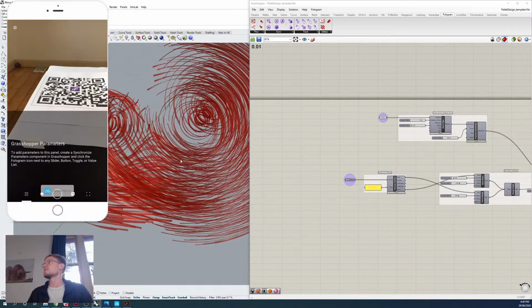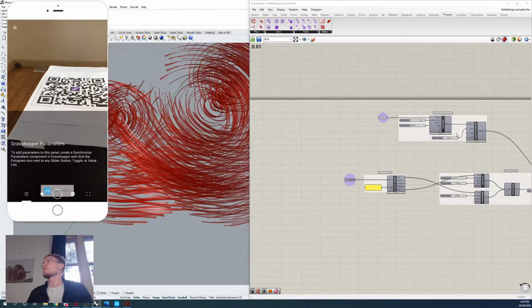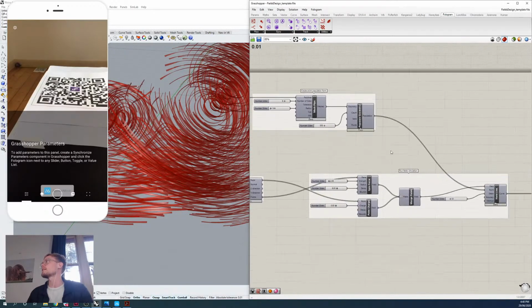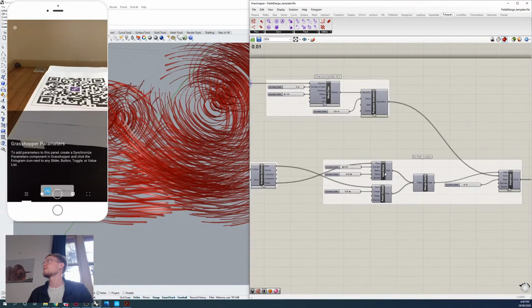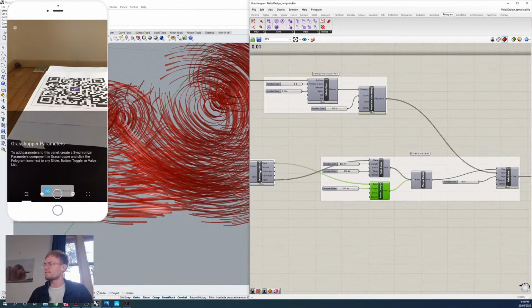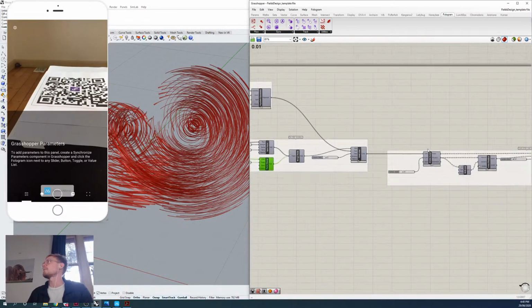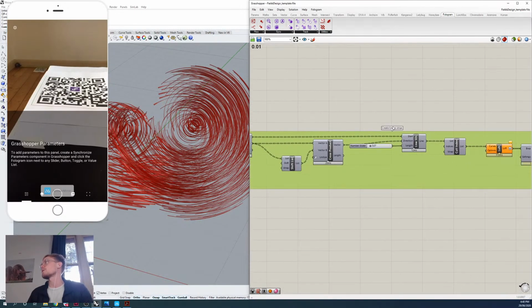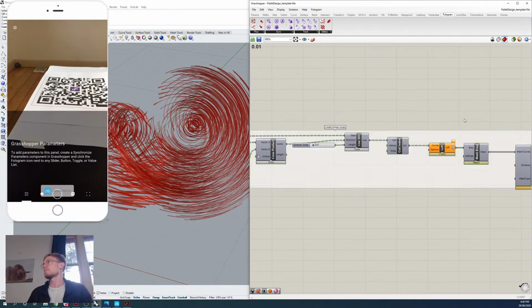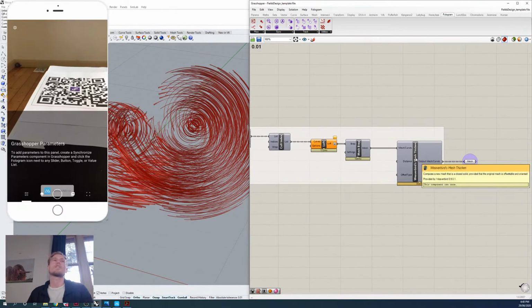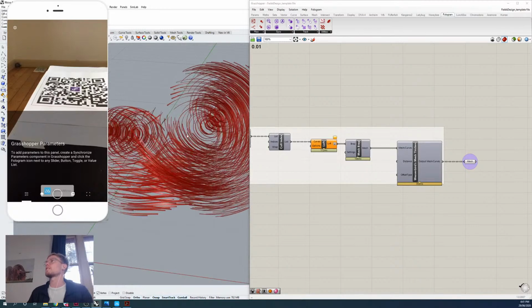Basically, if you've used the fields components in Grasshopper before, you'd be a little bit familiar with them. We're running a very simple field simulation with some spin forces and some point charges. That creates a field of vectors where we specify some starting points, and each of those starting points step through those vectors and create these long curves. Then over here in the definition, I'm writing a very simple timber strip behavioral algorithm, not totally optimized for fabrication, but it gives you an idea of what your timber strips might look like so that we can preview them.